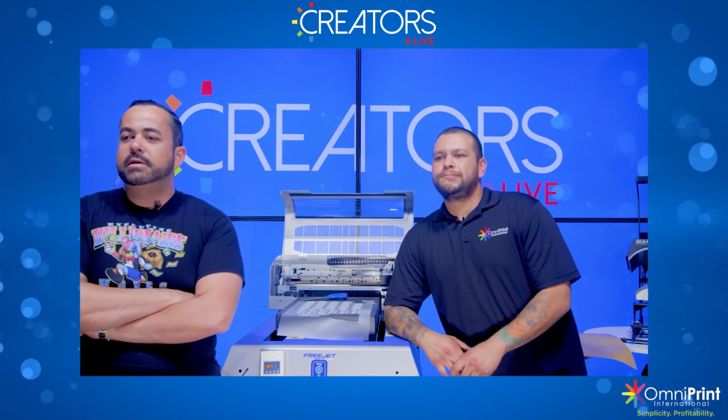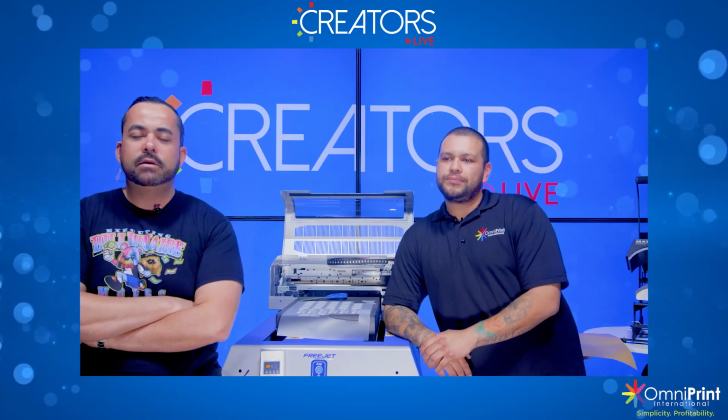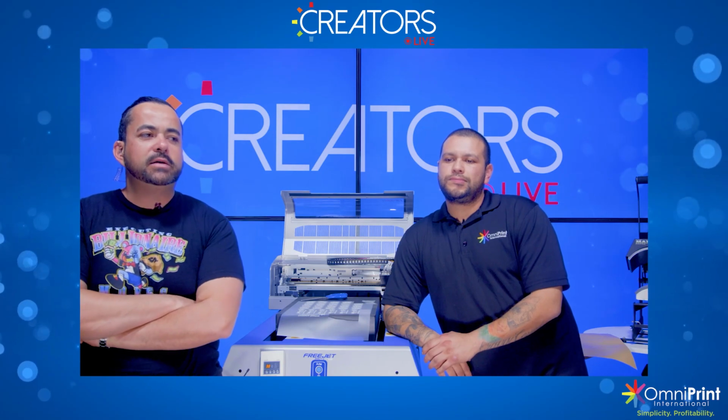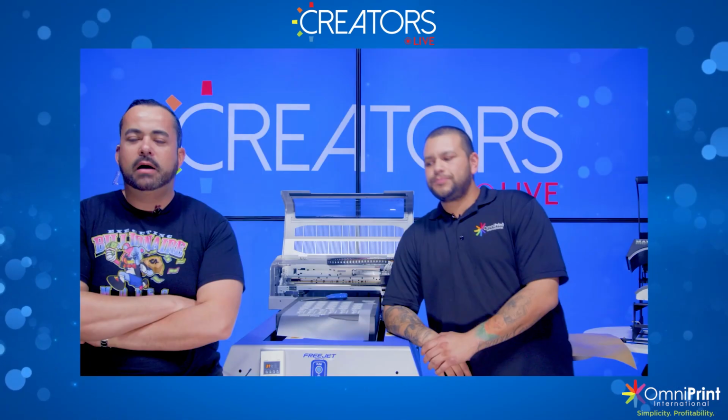After you hot peel, does it require another press? You can, but we haven't been doing it. It's not going to damage it. Have you been pressing over it, Mike? Yeah, I go back and press it for another 5 to 10 seconds, and what I notice is it does kind of soften the feel a little bit and dull out the shine. I usually just do 5 to 10 seconds, and it works fine. There's no issues.